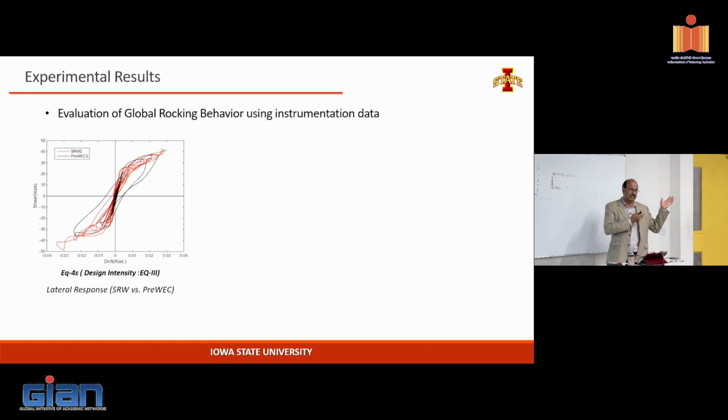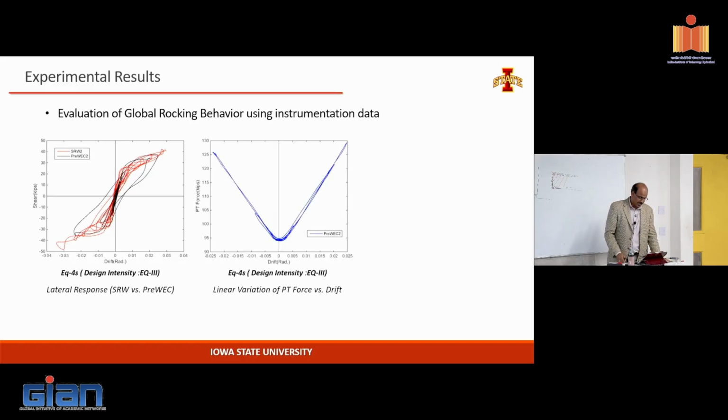So one is in the order of 18% damping. We eliminated that supplemental damping of 18%. So 15% we eliminated. The displacement went up by 20%, pick a number. The key is to maintain the post-tensioning force.